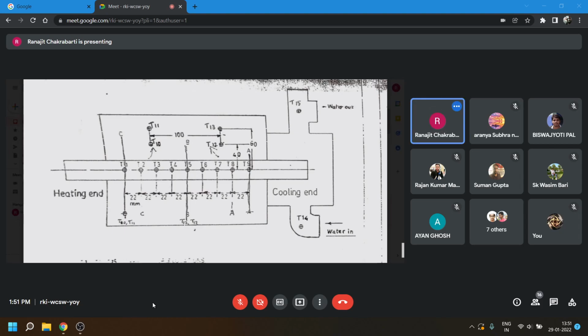This is a rod. Heat is entering through this section BB. You can see BB written here. Even if you cannot see the cursor, at least you can see BB. Heat is leaving through the section A. So we are making a heat balance. Whatever heat enters through section BB axially is equal to whatever heat leaves through the section A axially, plus whatever is the radial heat loss through the insulating powder from section BB to section A. Yes, sir, got it.